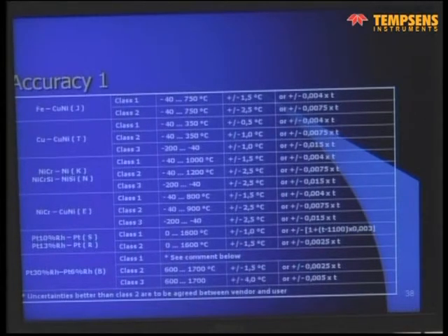This is because of a variation of the alloy. So normally if you like to have material which has the same permitted deviation at -100 as well as +500, you must tell the vendor prior, and he must select the material accordingly, which is highly costly.